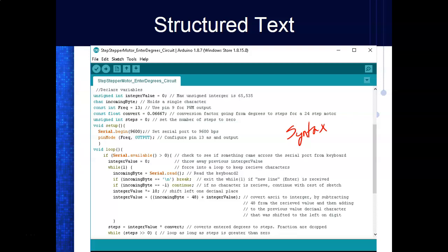So your computer, when you compile, will usually give you syntax errors that you have in your program. It doesn't mean the program's correct. Because if you used output 1 and you meant to use output 2, as long as the rung is in the right syntax, you're not going to get an error. So it doesn't know what you meant to do. It knows what the correct way of writing is.